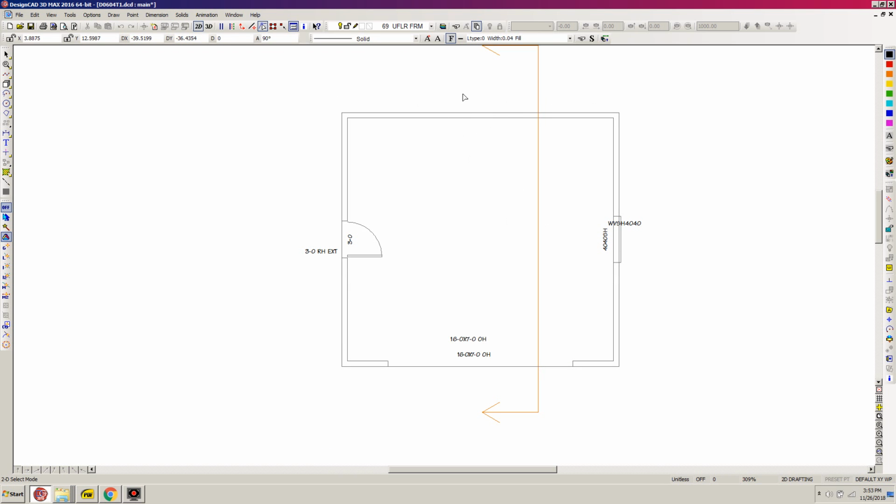So we know we're 24 feet long along this axis, and we've elected to run the joist along that long axis because we want to minimize the amount of loading we're putting on this header over this garage door. So we'll be running these floor joists on the long axis to accomplish that. I'm hoping that we can do our floor joist at 11 7/8 inch depth. I'm not sure what spacing it'll be or even what joist we'll be using at this point in time. Actually, I do, because I've already run this.